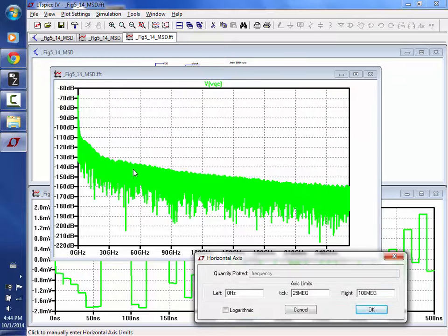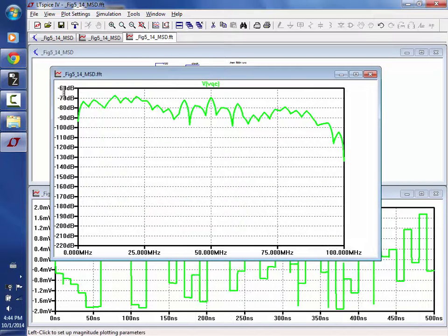Well, it's really small, but you see it's not magic. Our assumption that the quantization noise is band limited, DC to the Nyquist, isn't accurate. I mean, the noise is still going out here. Okay, so I'll hit OK. And I say, okay, my Nyquist frequency's right here. You can see, okay, with 70 dB, if we're down at 90 dB over here, that's a factor of 10 lower. So you could argue, okay, well, there's going to be error in what I estimate, but I want to estimate what the quantization noise is here.